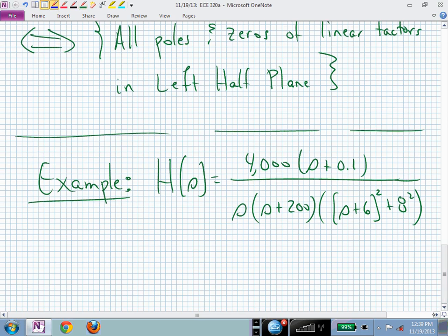What form is that in? If I ask you what form that transfer function is written in, could you tell me? Pole zero. You can see the pole factors and the zero factors explicitly. This is what we are calling our pole zero form. This is the form you would want to sketch it in the S-plane for the graphical H of s or H of j omega. But for the Bode plots, we actually want it in time constant form.